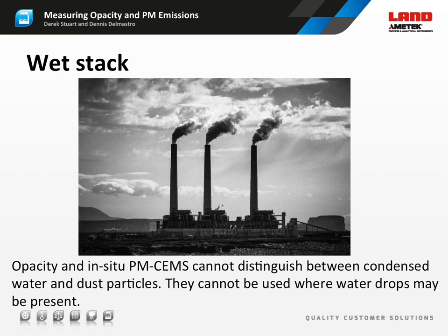In a wet FGD system, a slurry of limestone and water is sprayed into the flue gases. The lime reacts with the sulfur dioxide to form gypsum, which is a solid. The gypsum is then recovered and used to manufacture wallboard for building. The stack gases have lost most of the SO2 that is present, typically 98 or 99%, but they are now laden with condensed water drops. You can easily tell when a power plant is employing wet FGD because it has a dense, white, billowing plume of condensed water leaving the stack.